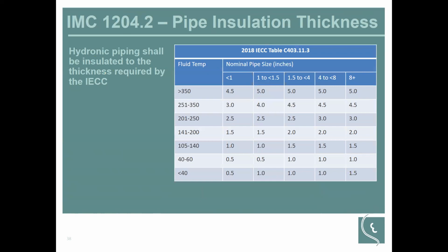That is something I would encourage if you have some large institutions. It would be recommended to actually go through the economics and develop your own pipe insulation thickness table based on what is cost-effective for your site, given your prices for energy and system efficiency, and develop a table like this for any large institution or an entity that may have several sites. It may be beneficial to put together to determine what's your cost-effective insulation.